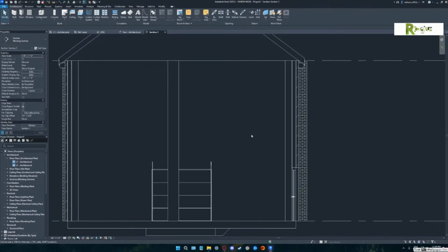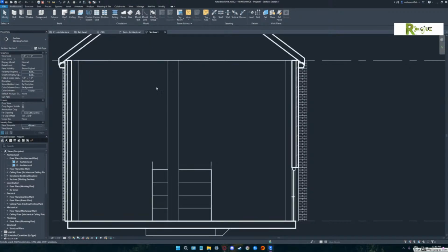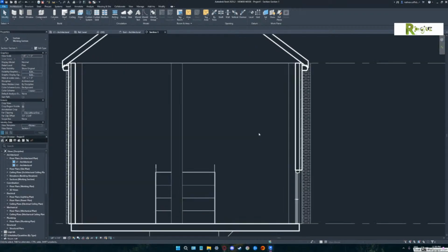Now the only thing that you do have turned off that I don't recommend is your line weights. Do you know where your line weights is? It's across the top. There's those little tiny tools at the very top. It's the third one up from the end. You have it turned on. That one right there. Hit that again. That's how it should look. Do you see how everything you cut a section through is a nice heavy line? All right. Now, if you zoomed out,